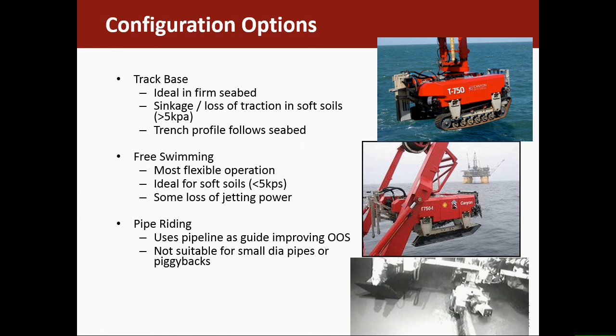The advantage is, on soft soils you don't have a problem with sinkage and slippage and so on, but the disadvantage is you do lose a lot of jetting power, because you've got to propel yourself with thrusters along the pipeline, and sometimes you also have to react against the water jets that are trying to push you up or down, depending on which way the nozzles are orientated. You've got to resist the pressure from the nozzles.